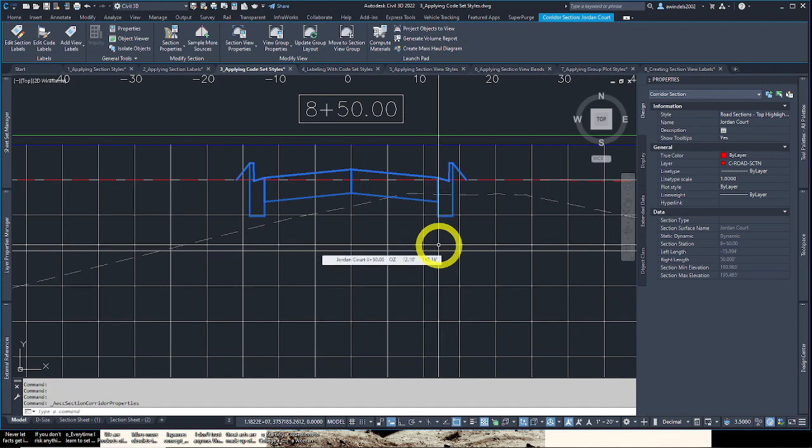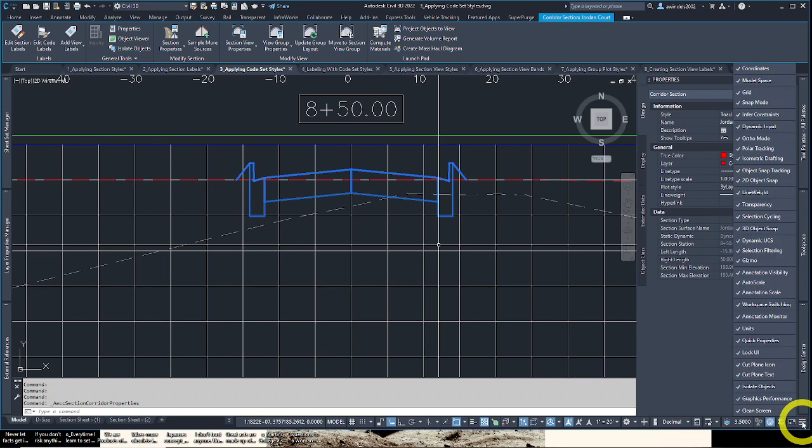In the lower right corner of the screen, let's go to, I call it the hamburger button, the customization button. It's a 3-bar hamburger button. And it wants us to make sure that line weight's turned on. As you can see, and this is good to know in general with AutoCAD, I call them the tray items and the customization hamburger button. I just turn them all on. The most important one it wants on is line weight for this exercise.